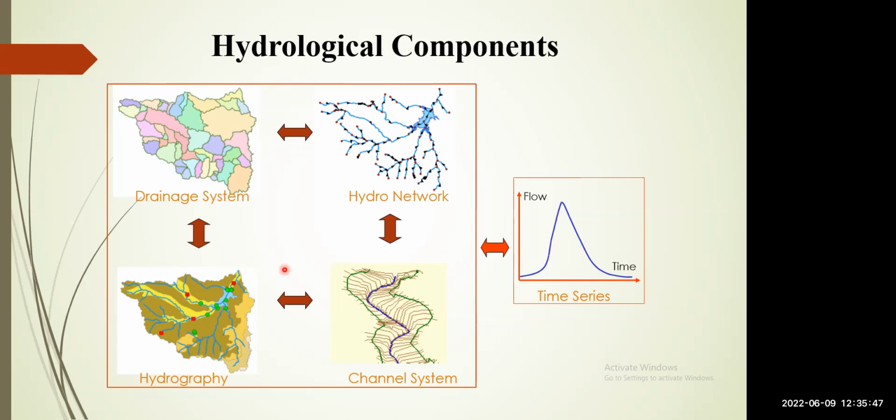It shows how the stream flow is calculated, and how the catchment area can be calculated using a detailed elevation model by including some other parameters as well. Whenever we have, for example, those green points, we can find the overall area. If I put a point here and want to know the catchment area till this point, it will be calculated from the back side like this, and then the overall area. That is the whole process we are talking about today, and we will explain it in the next slides as well.